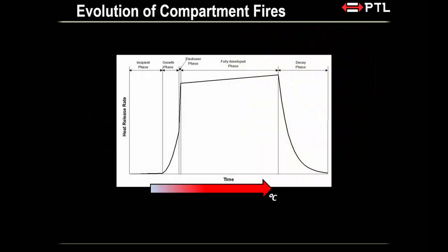Now, why am I telling you all this? Because this technology of measuring fire size to heat release rate is only about 40 years old. Before that, we used to believe that temperature is the proper measurement of the power of fire. But at one point, we realized that as the fire gets bigger, the temperature doesn't go up. It just stays around a constant value.